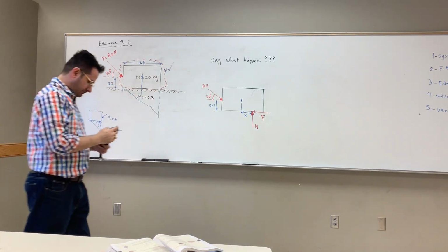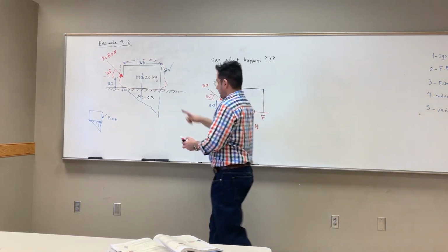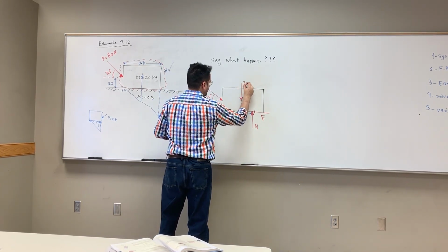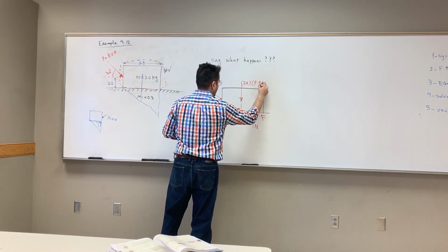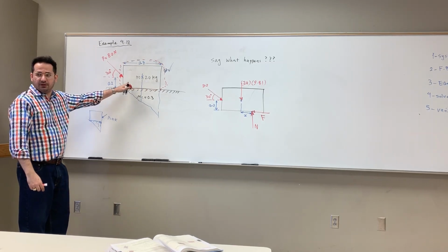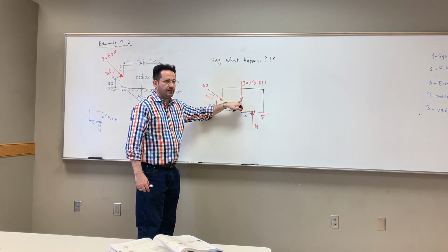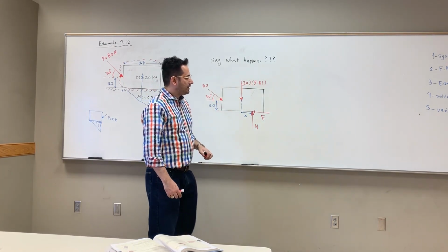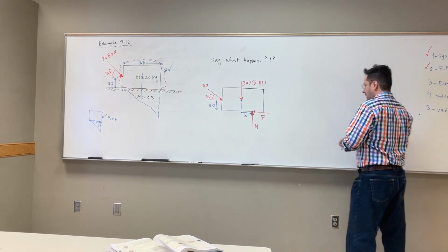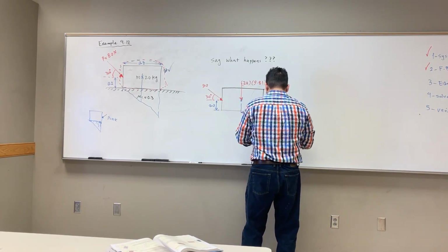Now, what about body force? Do I have a body force here? Yes. The body force is 20 times 9.81. Assuming this box is uniform, it acts at the very center, the geometric center, right? So that's my FBD. Don't forget, I showed my system and FBD. Now I write my equations. Summation of forces.